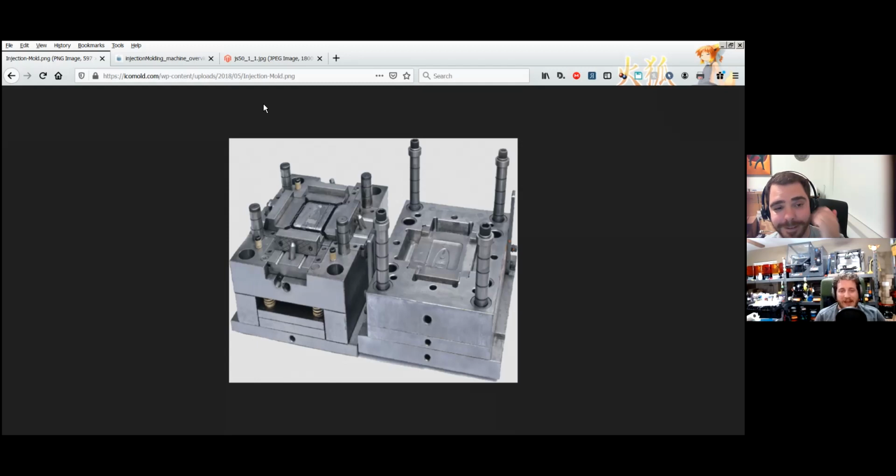It's really, really cool. And that actually keeps the molds from leaking, because otherwise it'll shoot out the sides. Yes, and there are some great horror stories and pictures online of machines that have failed where the molds didn't line up perfectly. When you're injecting hot plastic into something that is that tight, or you're expecting it to be that tight, you can put a lot of force to it.